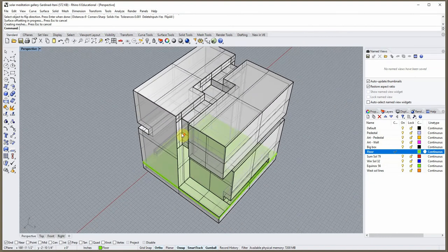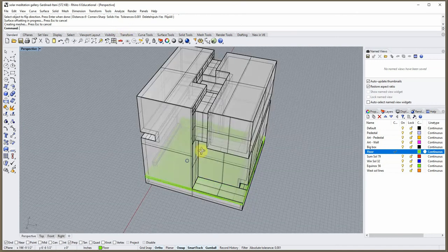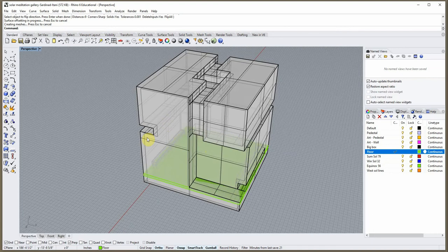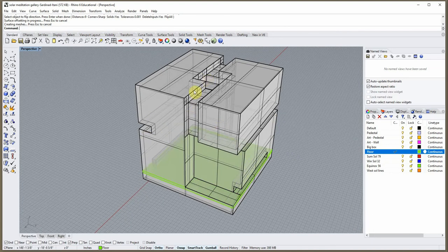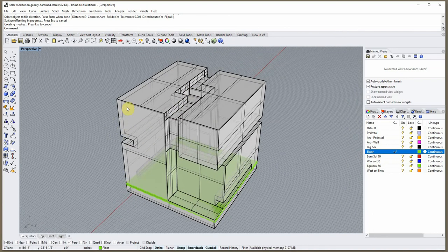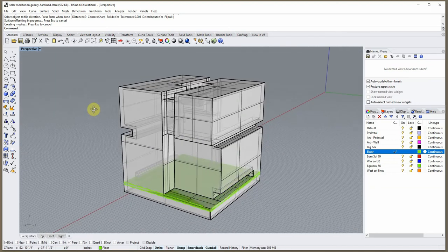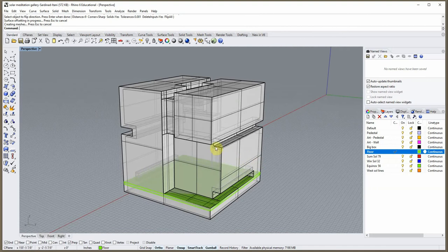Be very careful in this step, and I think in our 121 we talk about this. When you offset all surfaces for the entire box, sometimes it goes out of whack if all your angles are not perfectly 90 degrees. If your box is not a solid box, if you have holes in it, windows in it, things at an angle, it will not work. So please maintain your steps perfectly as you move along so you don't have any warped surfaces or angled surfaces when you offset the entire shell inwards.